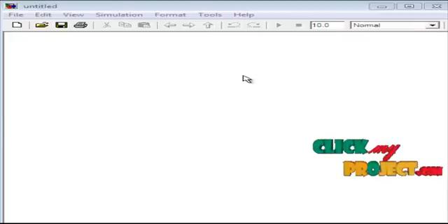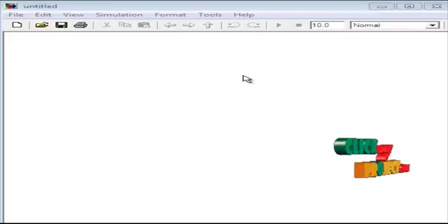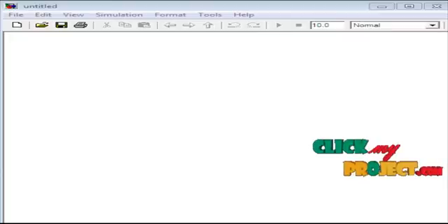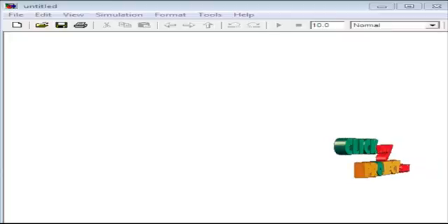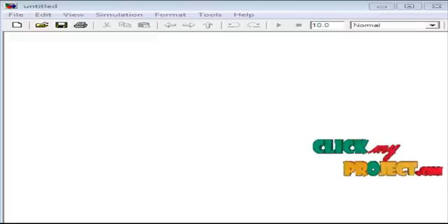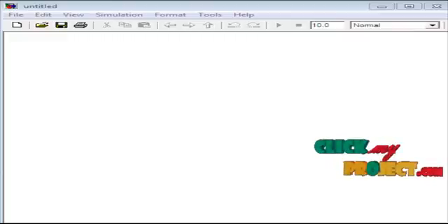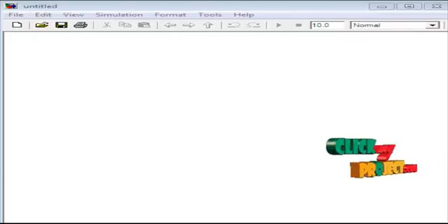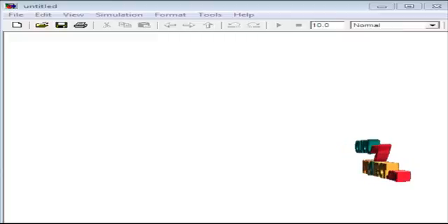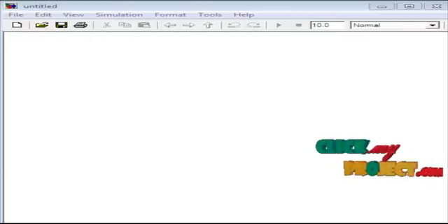And then the main controller, the PWM, pulse width modulation, is the main controller. And then the active clamp converters, its main steady state analysis. The soft switched active clamp converters combine the low switching loss characteristics of resonant converters with constant frequency characteristics.